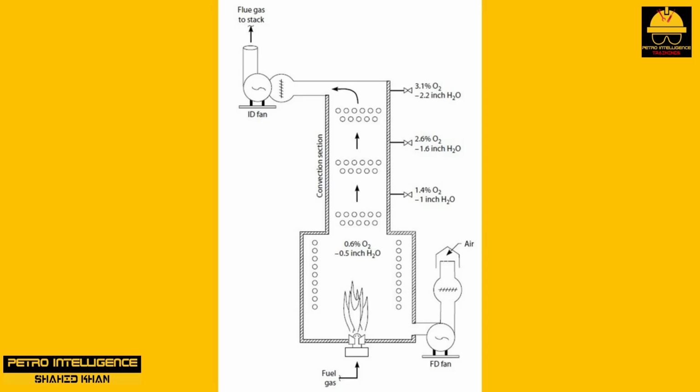The heat of the fire in the convective section expands the flue gases, causing a positive pressure in the convective section, which stops the air leaks. After some period of time, the fire in the convective section has consumed all the tramp air and is extinguished.